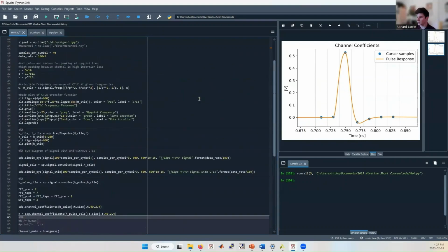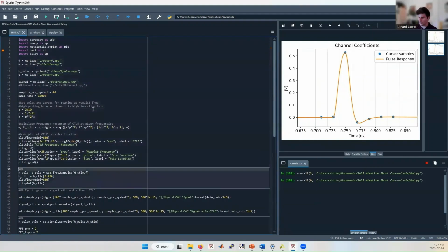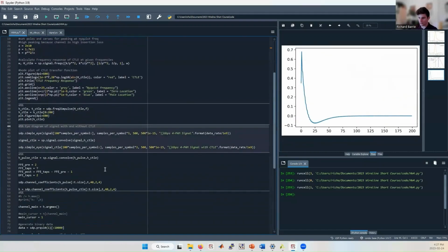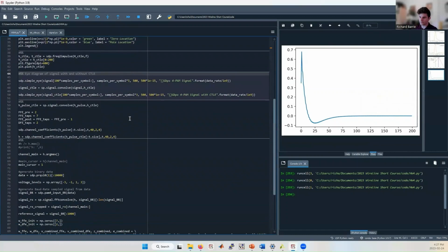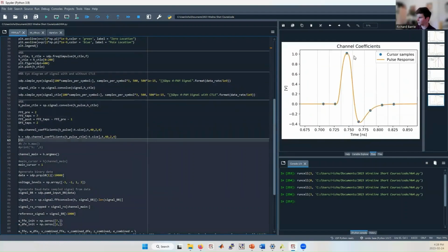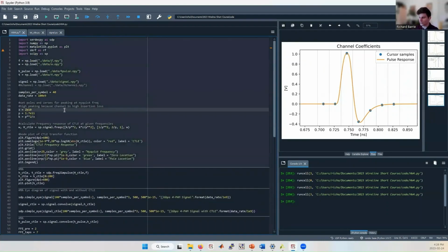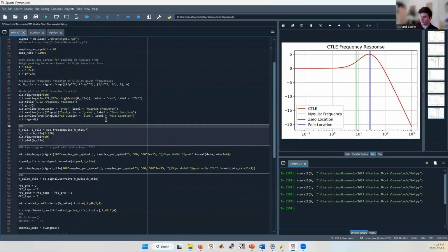Now, just as an aside, if you remember when we were doing a much higher boost, we can take a look at what our channel coefficients look like then. So here you can see much higher boost. We go all the way up to 1, but here we have a big post-cursor ISI term caused by the overshoot, and that's why the eyes in the eye diagram were completely not open. Okay, so going back to our normal gain setting,